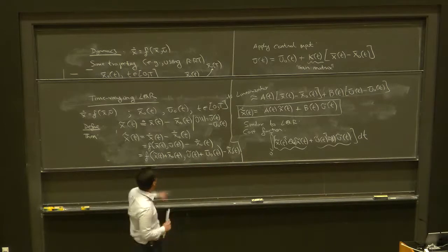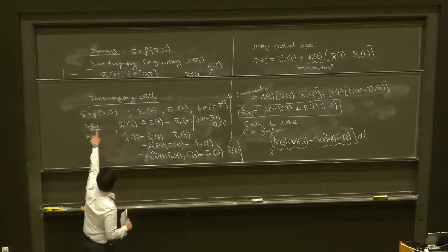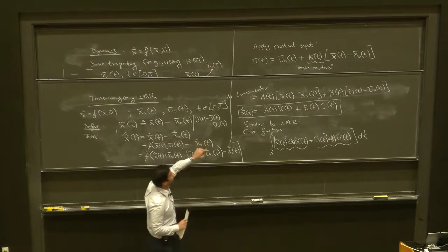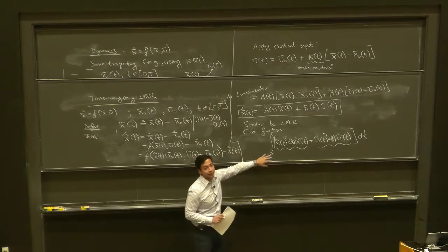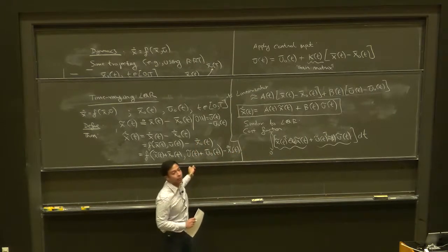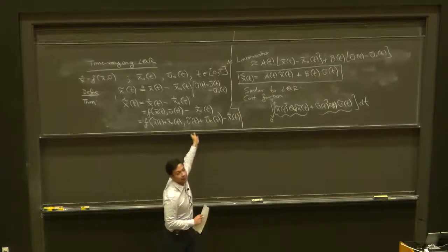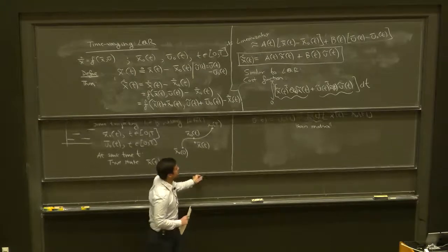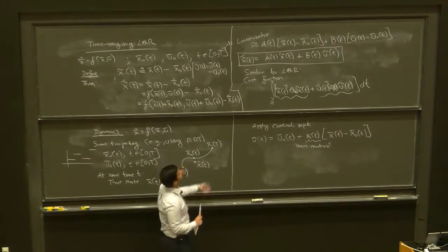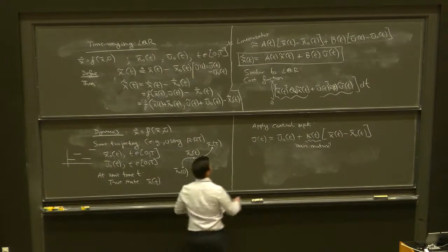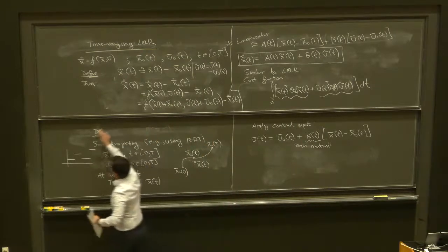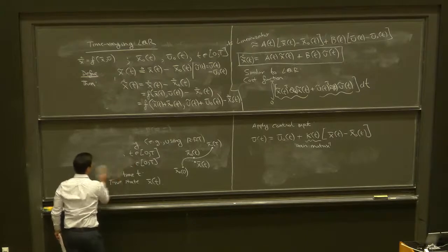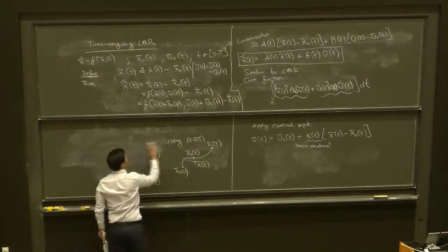If you have just these dynamics x dot equals f of x, u, and you try to find a feedback controller that optimizes this objective, that's not something one can do analytically for a nonlinear system. For a linear or linearized system, we can calculate a feedback controller that is going to optimize this objective.